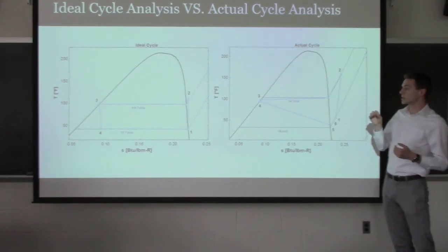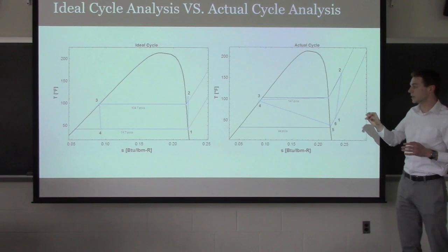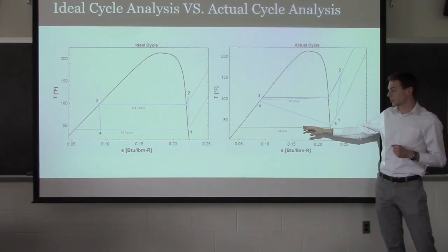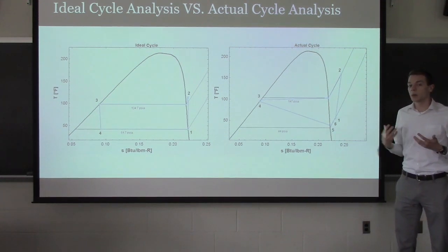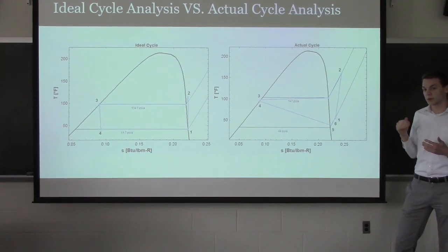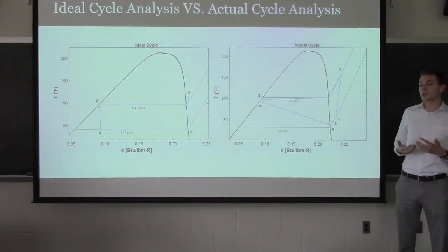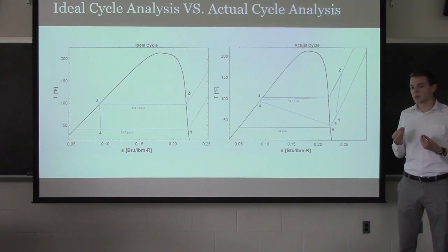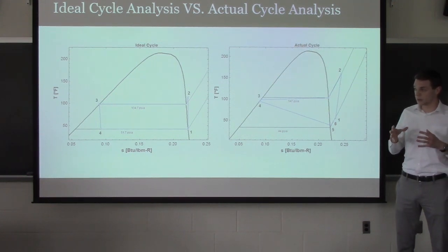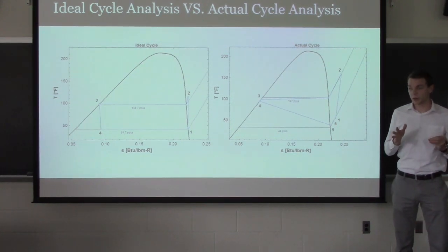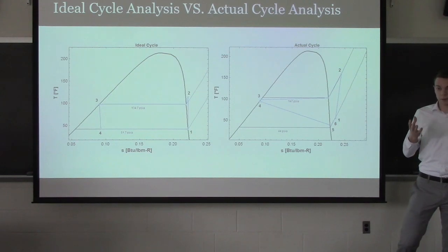What is not very similar is the 4 to 5 section. 5 really should be on the liquid vapor line here in the lower portion of the graph. We think we determined this to be because of too large of a pressure drop from the expansion valve before the evaporator. So if we were able to raise that pressure up a little bit, it would place position 5's mixture of the refrigerant closer to what we were expecting within the system. It works great. It's good the way it is, but it can come out better.